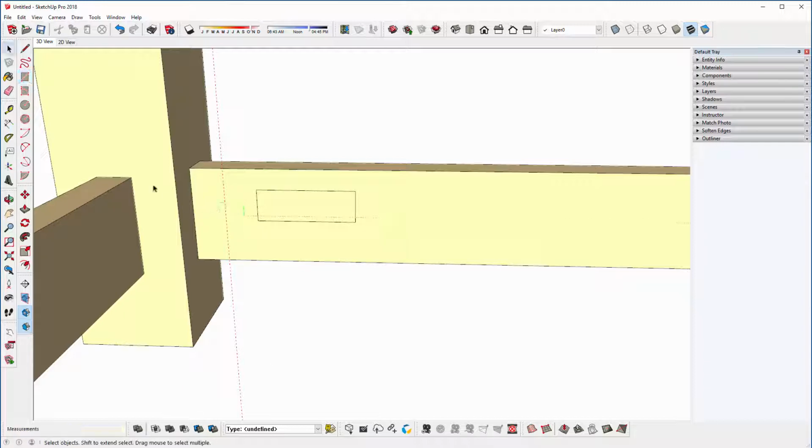That's good. Now, like before, I'm going to select the rectangle, then get the move tool and move it from the midpoint onto the guideline. Once on the guideline, hold shift and then reference the midpoint. So just go and touch the midpoint and click to finish.